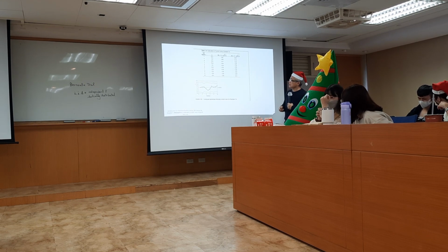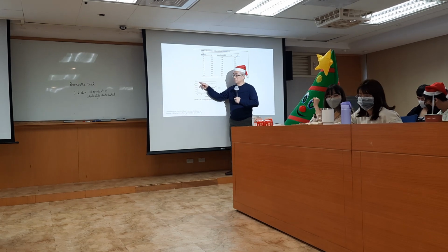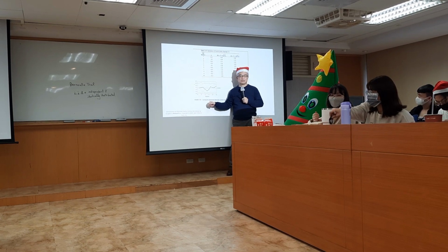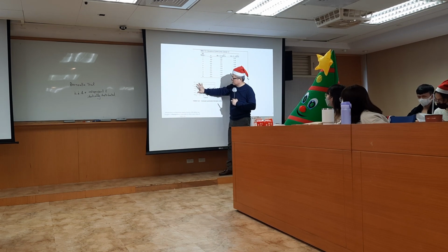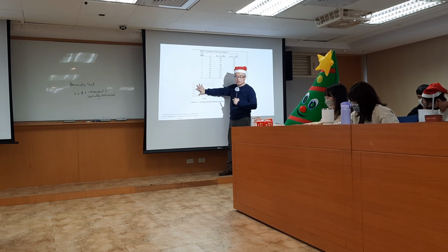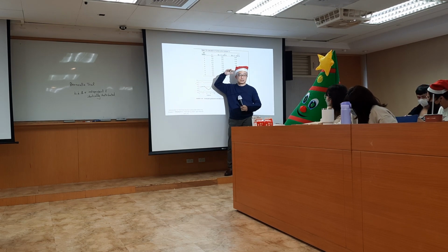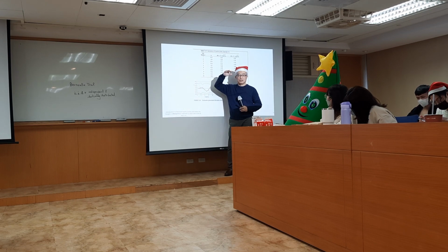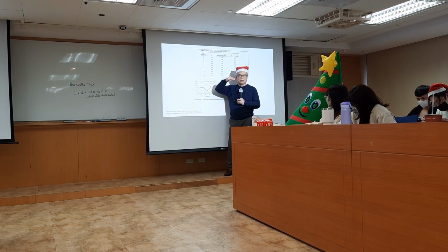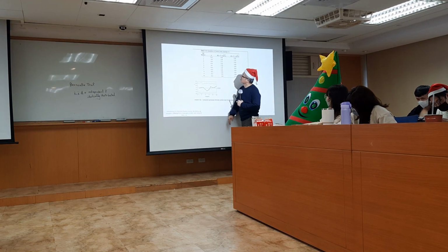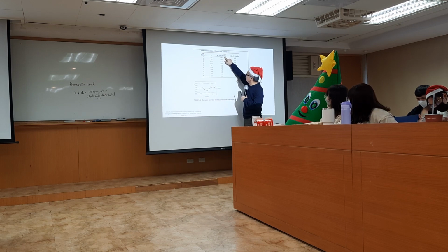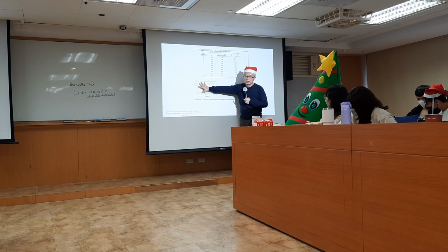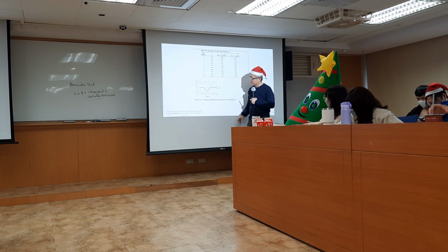So you can see this is like a jogging seesaw of the upper bound due to the sample size. With a larger sample size the limits are tighter, and with a smaller sample size, when the sample size is reduced, they get looser. If the sample size increases, it shrinks and becomes more compact. The limit is the average plus 3 standard deviations divided by the square root of ni. Since ni changes, the upper and lower bounds vary from sample to sample.